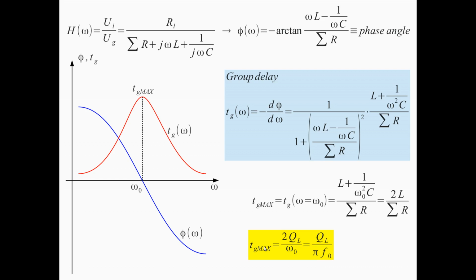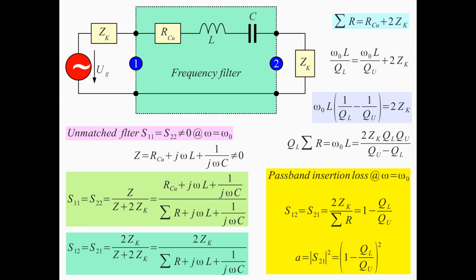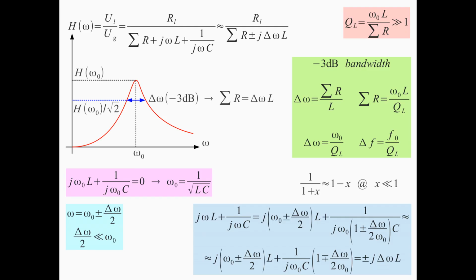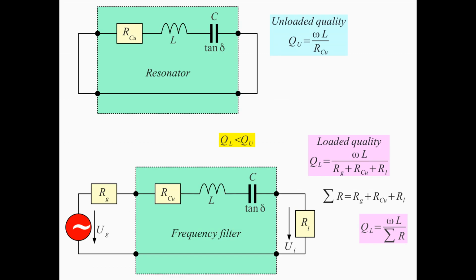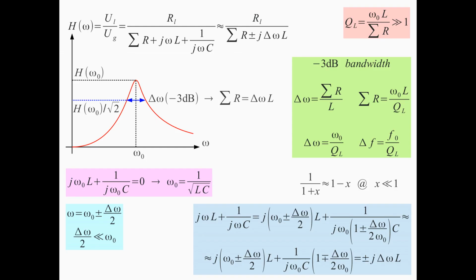Now, how are we going to handle filters? Of course, this is not the ideal filter we would like to have. The filter that has such a frequency response like here. This filter is only a single resonator filter. We have this 3 dB bandwidth, but this 3 dB bandwidth may not be large enough to filter our unwanted signals, say here or here.